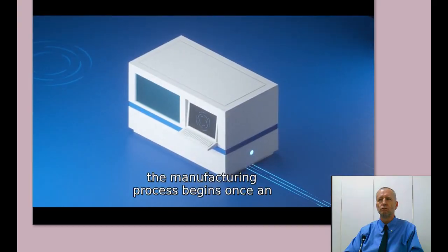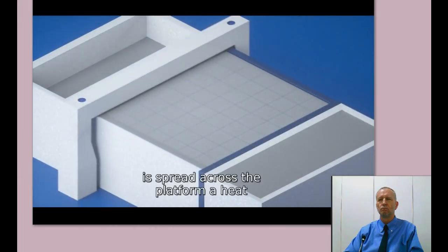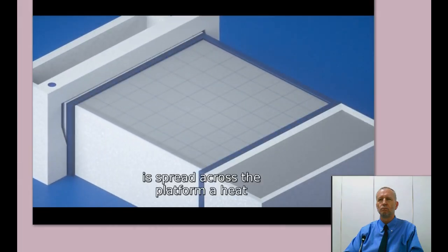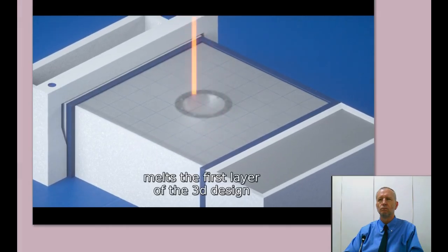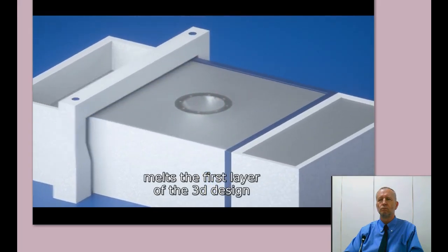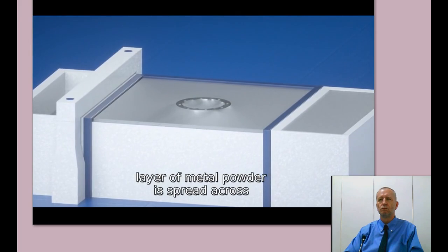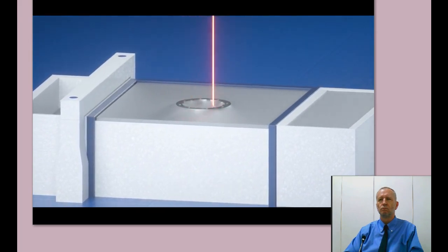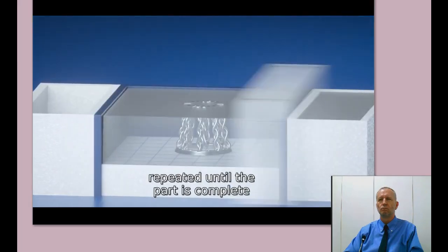The manufacturing process begins once an extremely thin layer of metal powder is spread across the platform. A heat source, such as laser or electron beam, then melts the first layer of the 3D design. The platform is lowered, and another layer of metal powder is spread across the platform. The layering and melting process is then repeated until the part is complete.